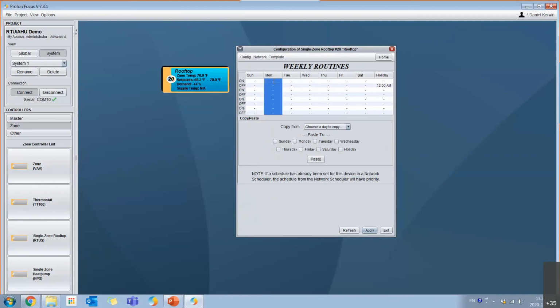So I could say on Monday, you become occupied at 6 a.m. And we have 4 on-off periods on any given day. So I could say, let's say I'll just choose off here. I want to go off at 8 p.m. And let's say it's a regular Monday to Friday type business. Well, I can just choose my Monday and I can paste it to the other days of the week right there. So if I leave it like this, on the weekends, it's going to remain unoccupied because it looks for any kind of change.